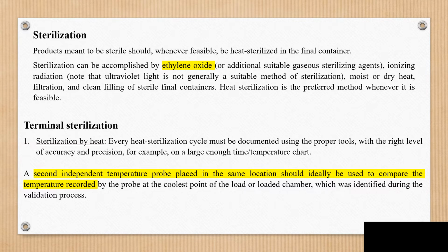First, we come on to sterilization by heat. In this, there is a primary temperature probe and a secondary temperature probe, which are maintained. The secondary temperature probe is maintained ideally to compare the temperature recorded by the primary probe at the coolest point of the loaded chamber, where the parenteral products are completely loaded.